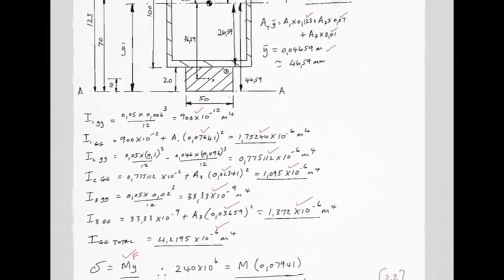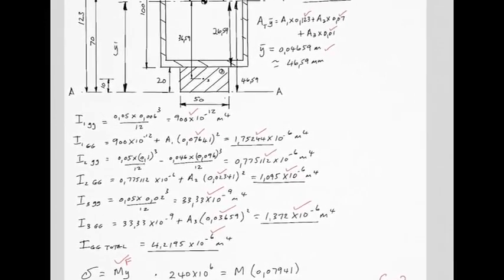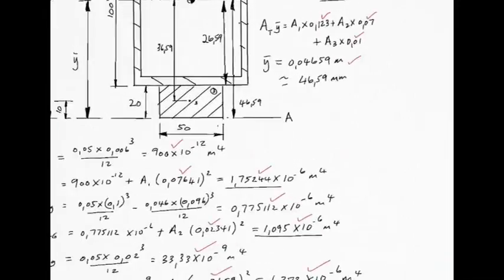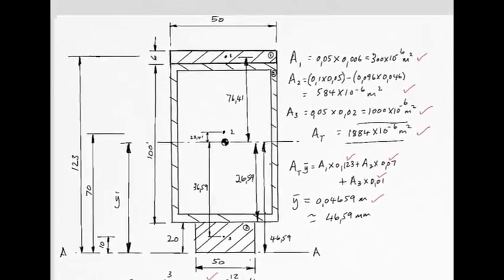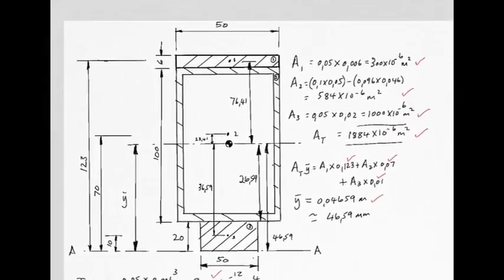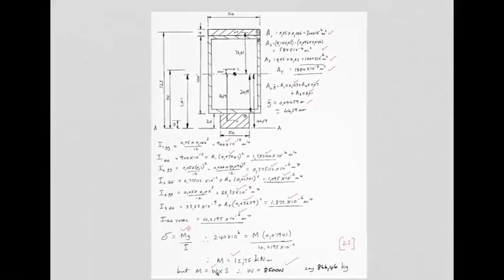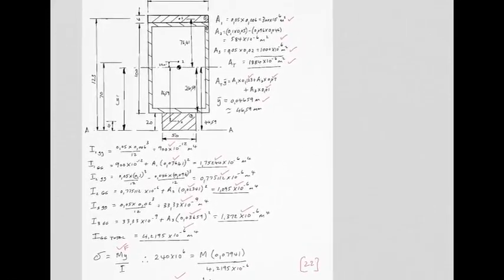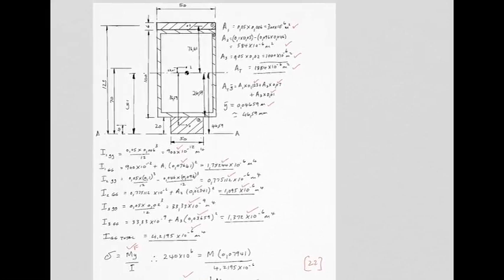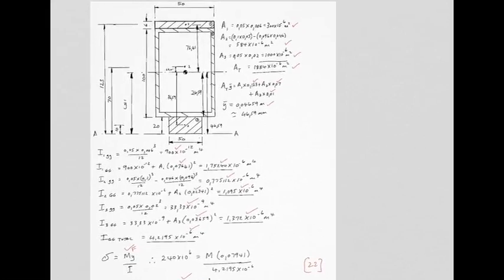Okay, lots of pitfalls, places where you can make mistakes, mostly with dimensions. So the key to this problem, and I've said this before, is the fact that you have a large, clearly dimensioned sketch with no ambiguity, so that you can read off it and get all these important dimensions that you need. Right, so now we go back to the bending formula, sigma equals My over I.